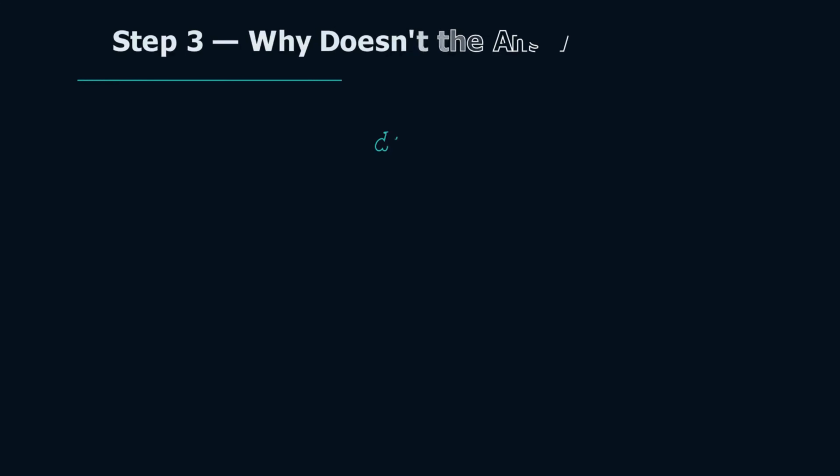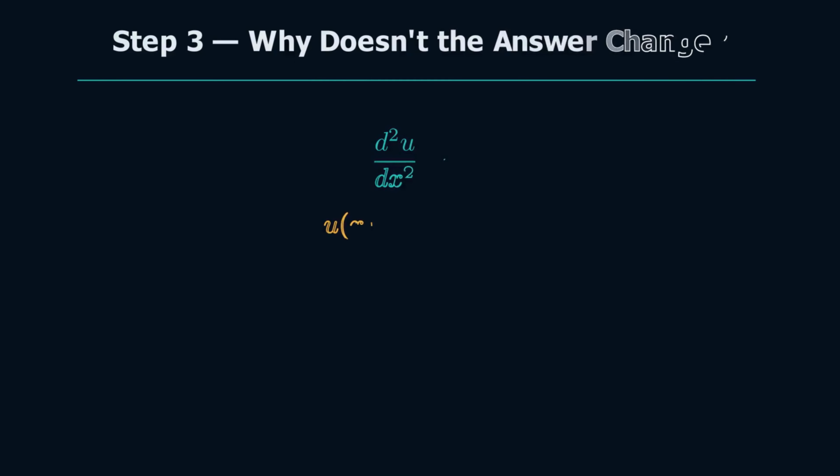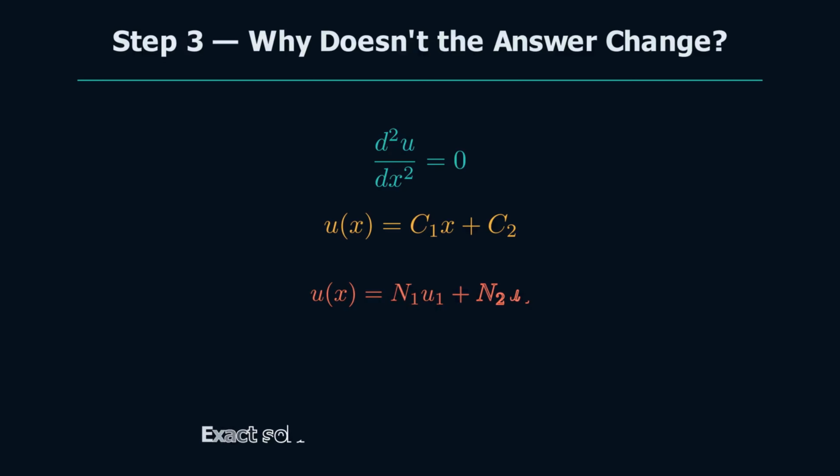The reason is mathematical. For a uniform axial bar with no distributed load, the governing equation gives a linear displacement field. And our 2-node linear bar element also assumes a linear displacement field inside the element. So the finite element approximation can represent the exact solution perfectly, even with one element.